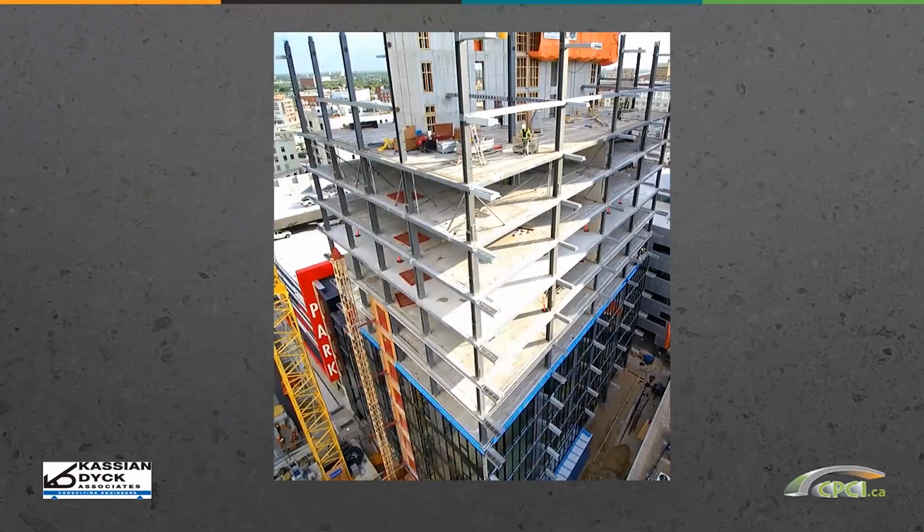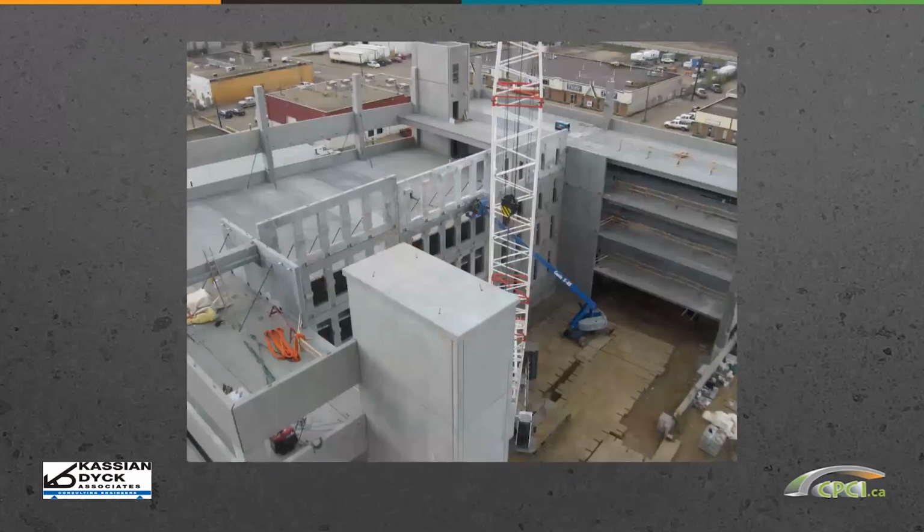So with Hollowcore diaphragms, again, we mentioned in any type of structure, they're going to be that horizontal floor or roof component that's transferring the lateral loads to the lateral load resisting system. What we're talking about today can be applied to other types of structures where double T's or other types of floor members are used as diaphragms as well. So a lot of what we're going to be discussing today are basic principles that could be applied to other types of structures as well.